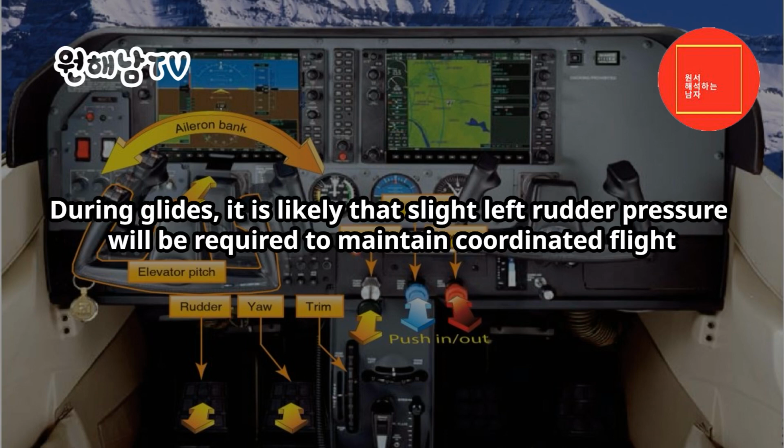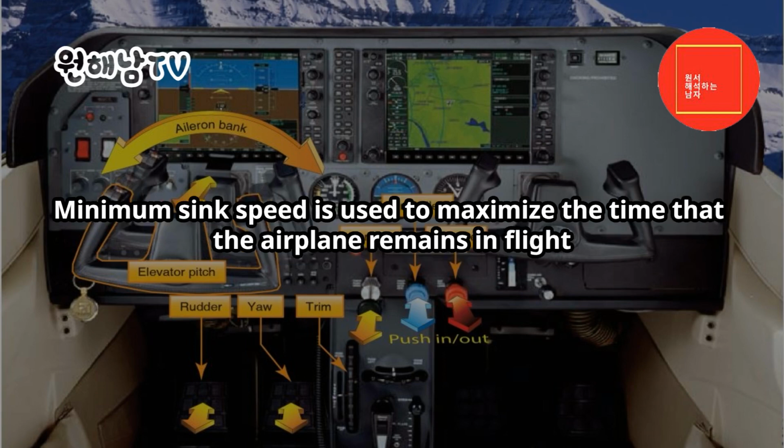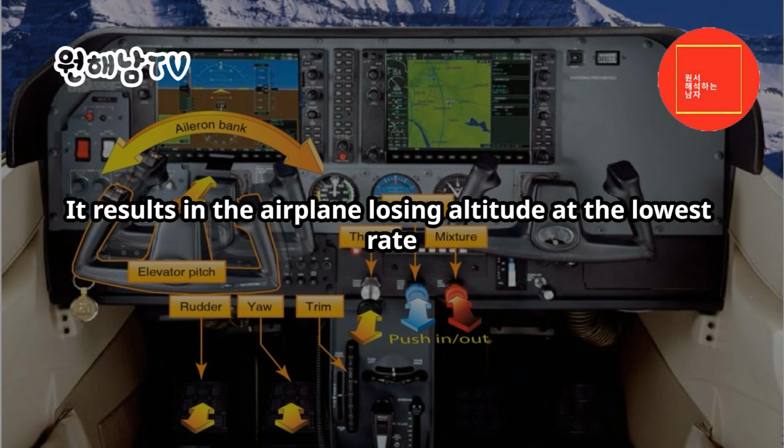During glides, it is likely that slight left rudder pressure will be required to maintain coordinated flight. In addition, the pilot needs to use greater deflection of the flight controls due to the relatively slow airflow over the control surfaces. Minimum sink speed is used to maximize the time that the airplane remains in flight.